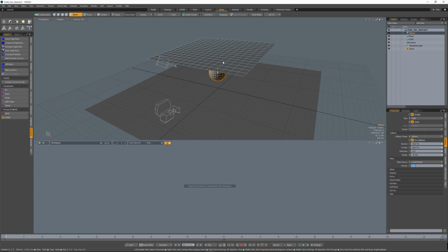But in the end, I'm not really going to end up seeing the sphere. So what I'm going to do for renders is I'm just going to hide it. It's just there as a stand-in object to give me some collision. And you can apply that when you're doing more complex cloth simulations as well. You don't have to have a character that, every little nook, cranny, and contour is going to collide with your cloth. You can set stand-in items that will do some of the collision for you to simplify things. And then those things will just hide at render time. And it's going to make your solve easier. It's going to give you an easier time working with your cloth. So that's a lesson you can apply to more complex scenes as well.